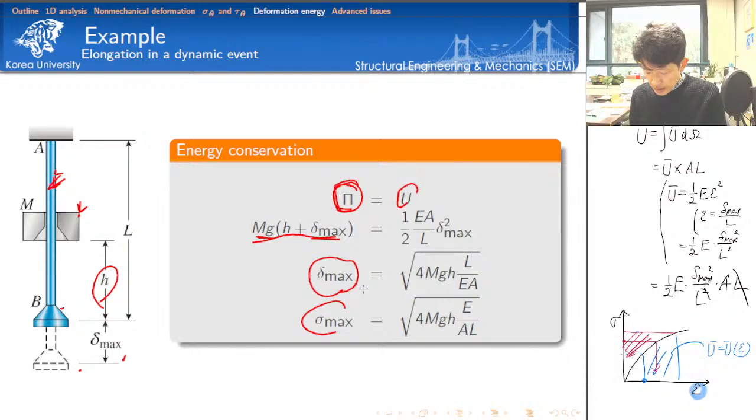This is called the complementary deformation energy density. Here, for the complementary deformation energy density, the control variable is stress. They are certainly different. In the case of linear elasticity, because the material behavior is a straight line, the numeric value of the deformation energy density and the complementary deformation energy density is the same. That's why it doesn't matter whether you use stress or strain as the control variable. But precisely speaking, when we talk about deformation energy density, the control variable should be the strain. Please keep this in mind. This is very important.